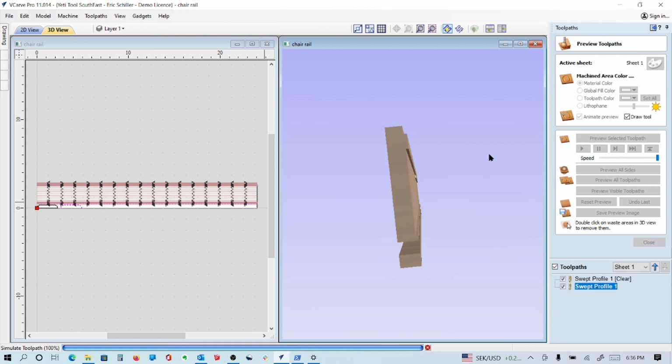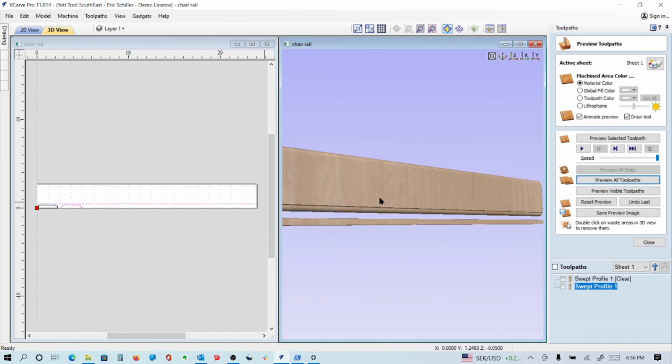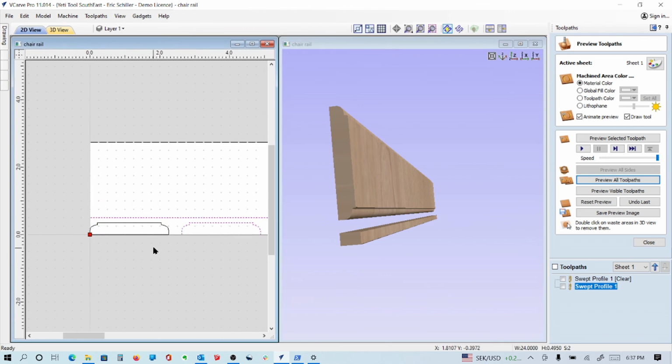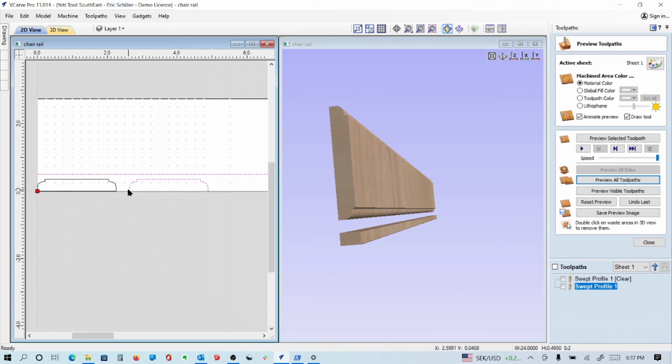And now it's surfacing it, taking that 50 thousandths off, and then we're coming in with the smaller tool, and there we are. So the issue on these is that you have to have a true cross section without the center line. Typically on a lot of CAD packages this would be inverted 90 degrees, and we would draw from the center line out but not use anything on the center line, and that may be the same logic that is here in VCarve, but we can't have a bottom on it. That's the only issue we had. So by doing that, it knocks it out.